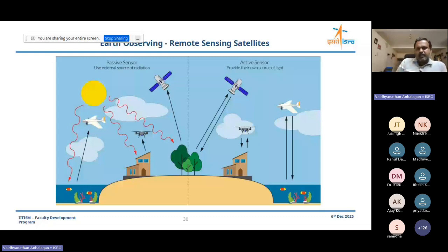So that is one trickier thing in optical satellites which are doing remote sensing. All these optical satellites will be put in a sun synchronous polar orbit, SSPO. But the basic thing here is it is only a passive receiver, an optical camera, that tries to take a photograph of a land which is lit by the sun. This camera has variable filters like IR filters, infrared filters, thermal filters. So with different filters, different information can be taken.